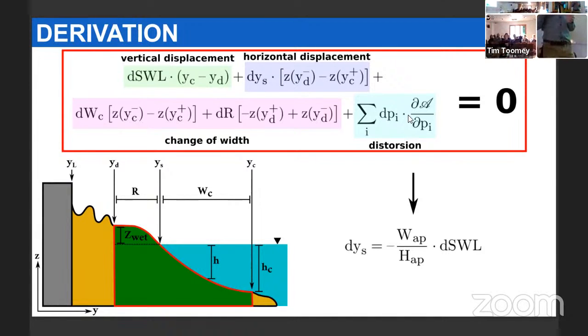Yes. So you could consider it as a changing shape then. Yeah. So if your profile depends on the sediment size, you could use this distribution, and assume that it changes depending on the fraction that is entering here. So you could change this distribution of sediment, and also update this characteristic sediment size that you use for the shape. It could be a way, totally.